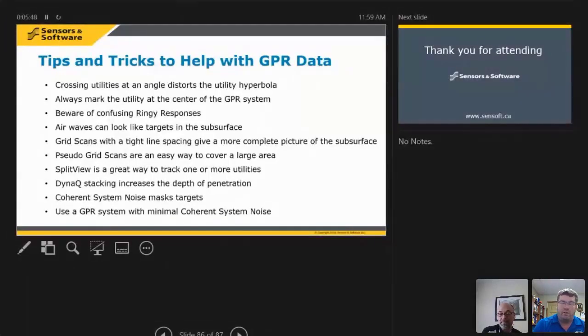Very good. And with the use of the radar outside, I am a firm believer in calibrating that velocity. I have had numerous employees over the years spend a lot of time looking for that beautiful hyperbola that, if they would have done that, would have known that they were getting the, I think as your example said, the street light in one case or the building. So I thought that was great.